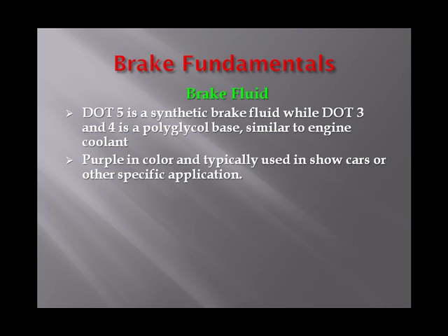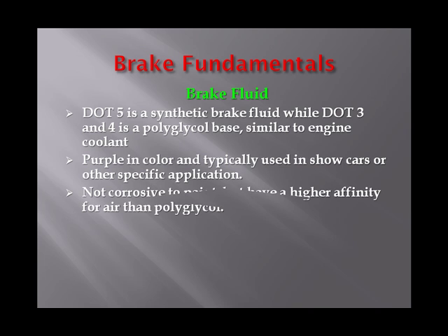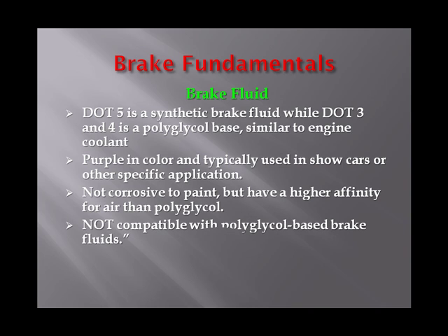DOT5 is purple in color and typically used on show cars or other specific applications. It is not corrosive to paint, but will have a higher affinity for air than polyglycol. And it is not compatible with polyglycol based fluids.